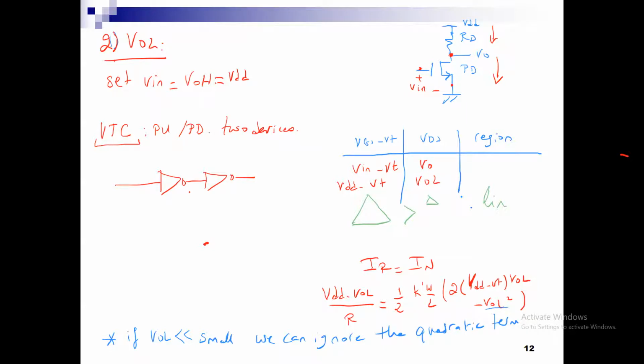I mean, if I have the first inverter at DC, driving the second inverter, and I'm performing the DC analysis, what is the current that flows into the gate? I have infinite impedance, right? So I study the inverter itself as a DC characteristic, but only the two devices. Is that your question? Yeah, that's my question. Okay, excellent.